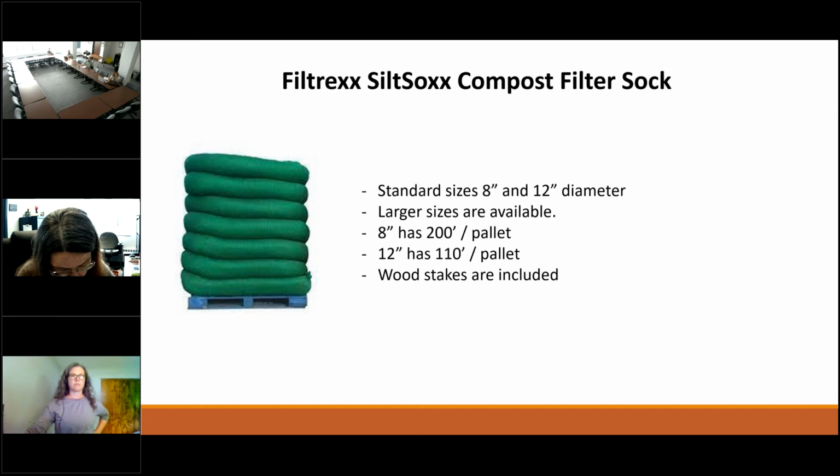So typically in your installation, it's a much easier deal. The sock is simply put in place, just laid in its position where you need it, and you come through afterwards and drive a stake in through the sock and into the soil. That's all it takes to hold it in place.